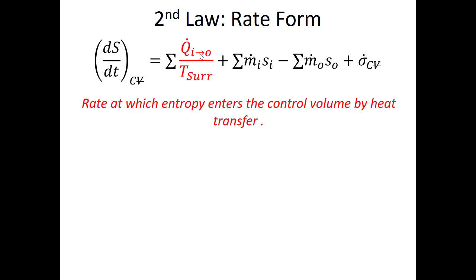There is some heat transfer, so you have to think about the sign for the heat transfer. It gives a couple of different temperatures, so you have to think about which temperature to pick and what units it should be in. You don't want the temperature inside your control volume. You want the temperature at the boundary or outside of your control volume. Then you'll have to find m dot times delta S. You can fix the state at the inlet and the state at the outlet, and that should tell you delta S.